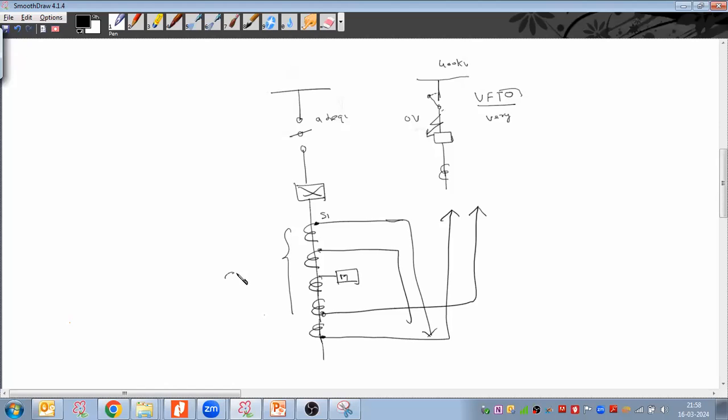So what I'm doing is core splitting, meaning out of 5 cores I'm putting 2 cores over here. This is what you are trying to tell, right? 2 cores or 3 cores? I'm putting 2 cores, not 3 cores. Exactly, 2 cores. Yes, sir. Let me draw this single line diagram again. All of this I'm discussing from the SLD point of view. My CT sizing calculations have been discussed, but this is for the SLD representation. So 2 cores above the breaker, then 3 cores after the 2 cores before the breaker, and 3 cores after the breaker.